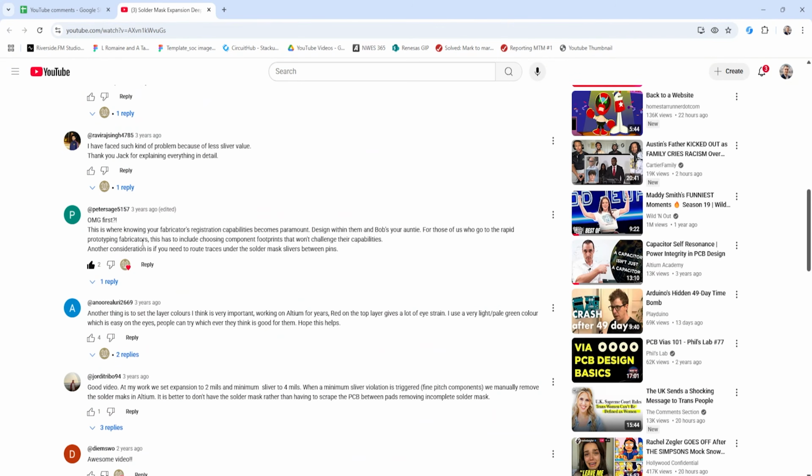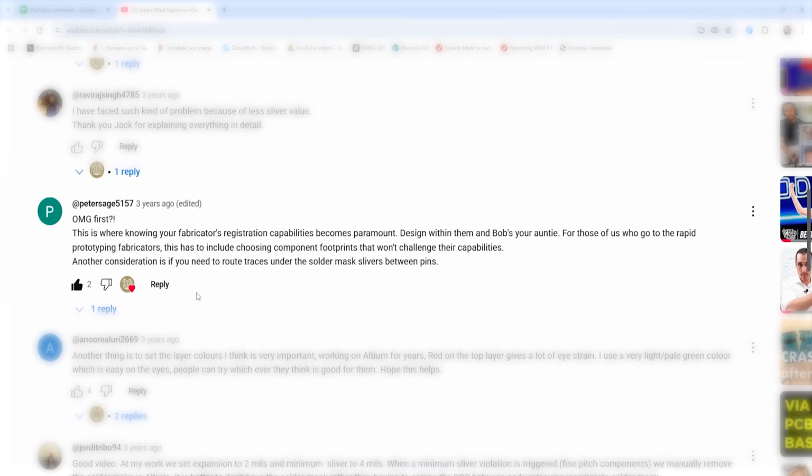This first question comes from the older solder mask expansion deep dive video, and this question comes from superfan Peter Sage. Peter writes, "Oh my god, first! This is where knowing your fabricator's registration capabilities becomes paramount. Design within them and Bob's your auntie. For those of us who go to the rapid prototyping fabricators, this has to include choosing component footprints that won't challenge their capabilities. Another consideration is if you need to route traces under the solder mask slivers between pins."